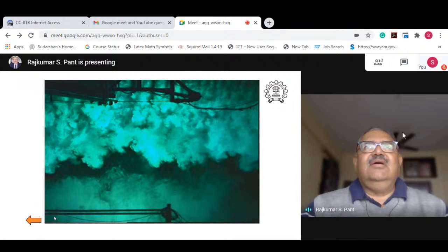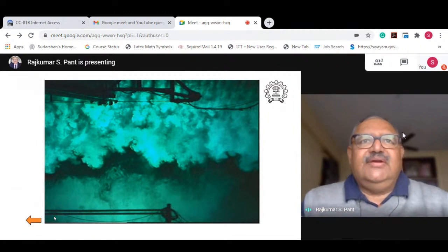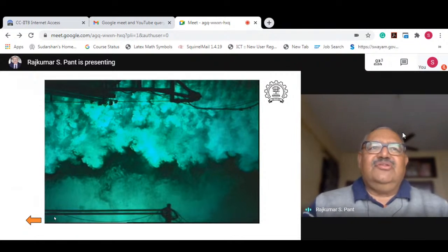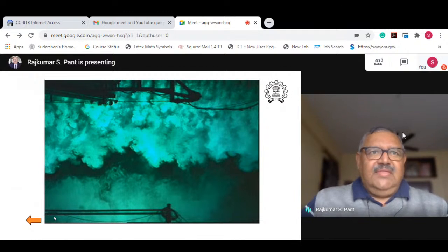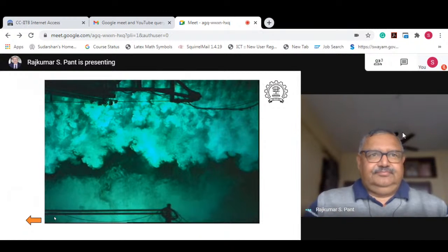And when the model of the aircraft passes through the sheet, you can look at the wing tips. At both the wing tips, the air actually starts curling inwards. And when you couple that with the forward velocity, it starts going into rotation. A lot of the energy of the free stream is consumed in creating those round vortices.